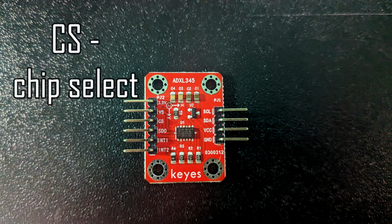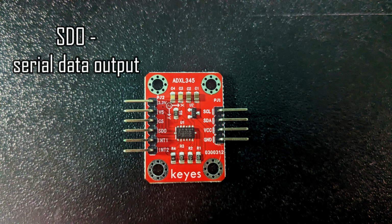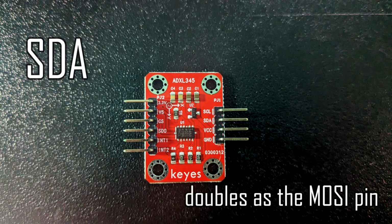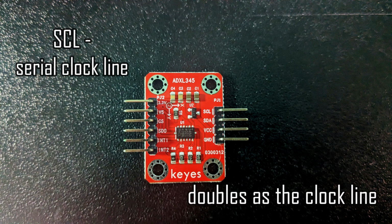chip select for SPI communication, INT1, which is hardware interrupt pin 1, INT2, which is hardware interrupt pin 2, SDO for the serial data output pin, which doubles as the MISO pin for SPI communication, SDA for I2C communication, which doubles as the MOSI pin for SPI, and SCL for I2C communication, which doubles as the clock pin for SPI.